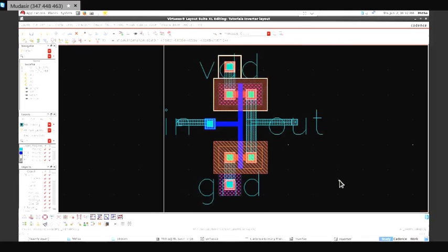The layout is done. Now, it's not done, we have to go for connection and placement. First, when doing placement, I place different transistors to see how I can make symmetry in my layout, so that parasitics will be reduced. Then I'll do connections. In connections you can also keep this symmetry in mind. Now once this is done, I'll save it.